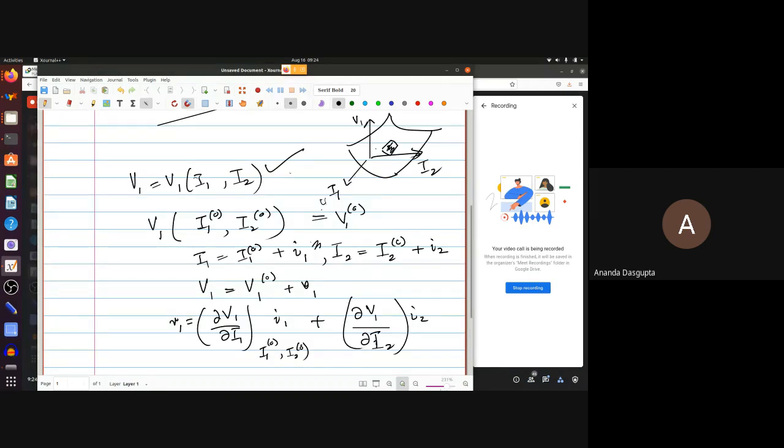Using the Z parameters to solve the Wheatstone-Bridge problem is a typical example of an overkill. You don't really need it, but you can use it. Later on, when we talk about transistor equivalent circuits and so on, especially when we talk about design of the CE amplifier, the common emitter amplifier, there this will be very, very important. And there, we will really be talking about a true AC equivalent model.